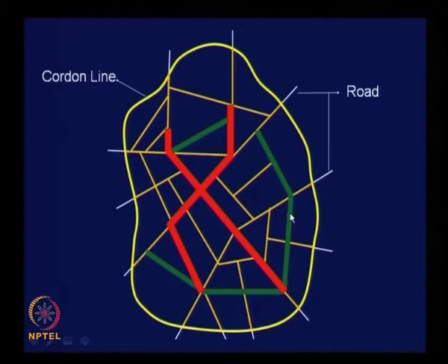What about the green ones? If you are recommending, let us say, a metro rail system along the red colored corridors, maybe the green ones being heavily trafficked roads next to the red one, you can think of a good bus system, feeding traffic at regular intervals to the metro as well as meeting the natural demand for transit.